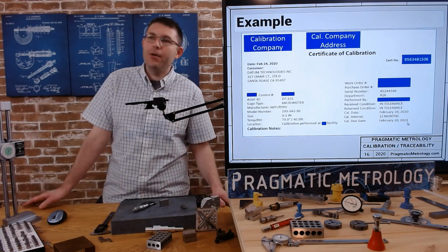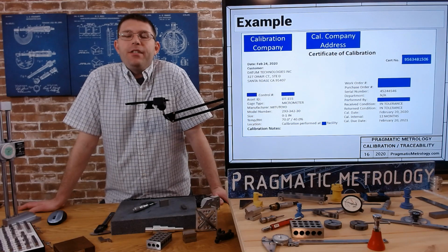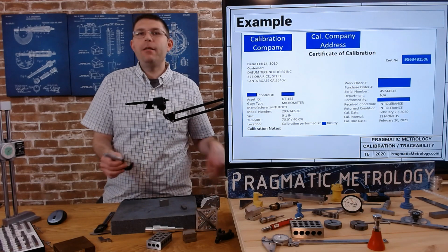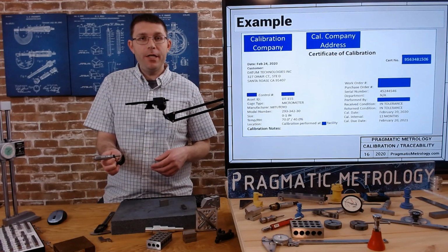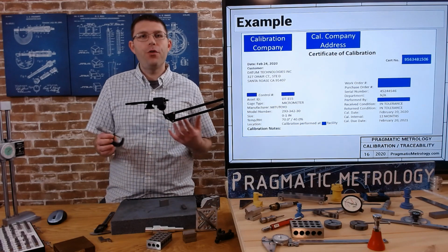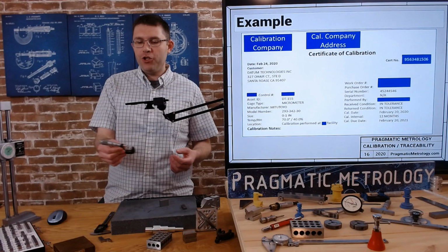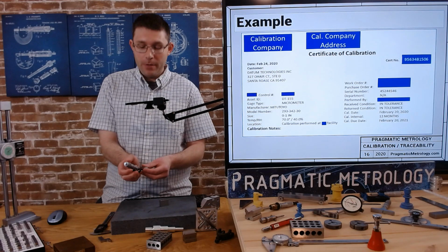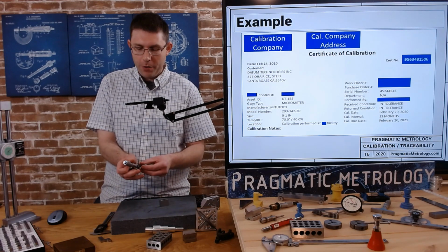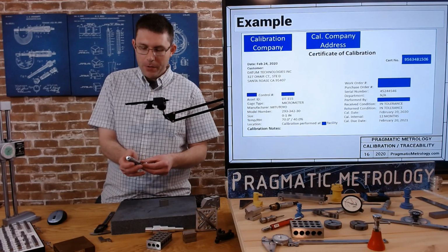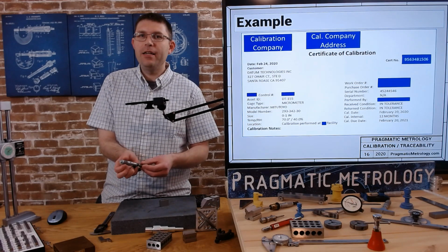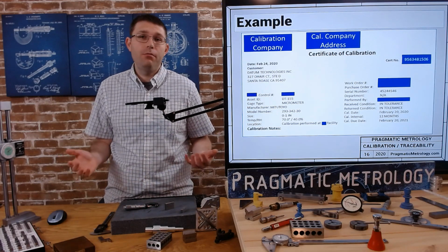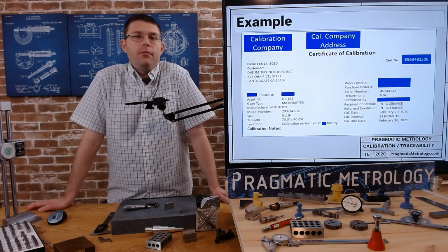So this calibration is a different approach than what I've explained to you. I said I like to do these in-house every 3 months. Datum Technologies is sending these out every 12 months. And I could justify both approaches. I know Datum Technologies will be checking their micrometers with a standard before they use them. So they're not waiting 12 months and never checking their micrometer themselves. But they want that extra traceability, that extra security in having a third party verify their micrometer once a year, which is a great way to do it. I'm not going to complain about that at all.